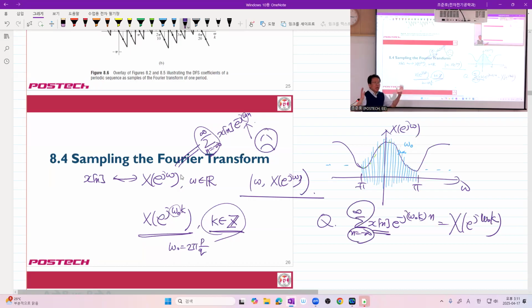You need the entire signal. What can you do? How can you handle the DT signal, the mathematically modeled DT signal, using our finite memory computer? Truncation, right? So maybe you just want to replace this by some m, so you have 2m plus 1. Saying that, okay, from negative m to positive m, almost all the important signal components in X are contained, right?